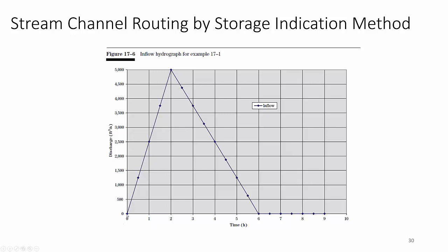And the area under this triangle is 1/2 base times height. The base is the time of peak and the total duration minus time of peak, from the time of peak to the end of the storm, times the height, which gives you the area under the curve. If you quantify these areas and it's much larger than the total Q after a 6-hour event, you can reduce this by simply bringing this triangle in and adjusting it until the area under the curve aligns with your Q. You can do this in Excel very easily. Typically the rising limb is more linear than the falling limb. The falling limb tends to be more parabolic.